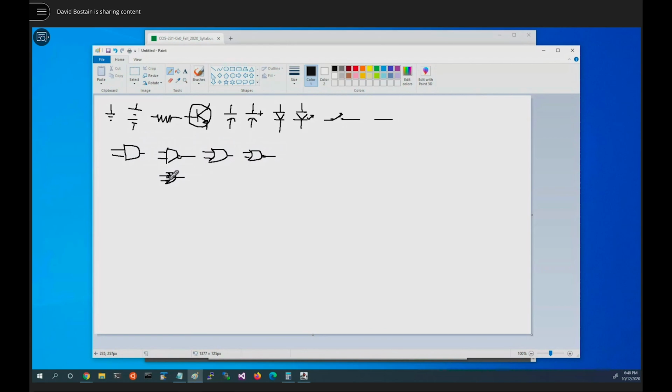That's the other picture of an AND. And this is another picture of a NOR gate. Remember, the De Morgan form: this looks like an OR, this looks like an AND. Looks like an AND, that looks like an OR. Bubbles are on the input, not the output, when we deal with these.